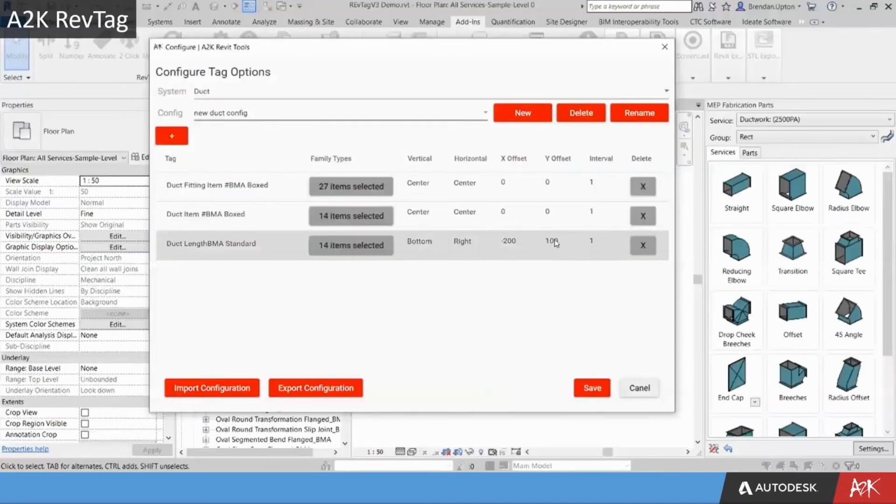And in a similar kind of vein, A2K's RevTag Revit add-in provides model modifications and annotation, but in this case for MEP system elements. What is otherwise a fairly slow and tedious process, the split feature contained within this tool firstly splits long duct lengths into manufacturer-specific lengths and then tags them accordingly.